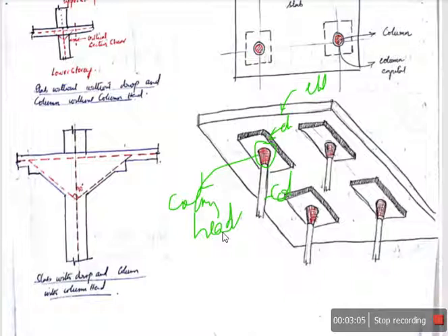Where you have huge spans, we can expect this in commercial buildings, warehouses, and the like. In commercial buildings where a beam is aesthetically not good in appearance, if you want to remove that beam, there is a slab which you can use, and that slab is nothing but a flat slab. So a flat slab is normally used in commercial buildings and warehouses. The design is different.